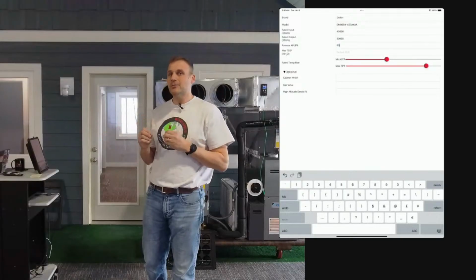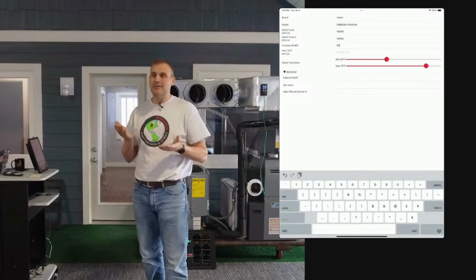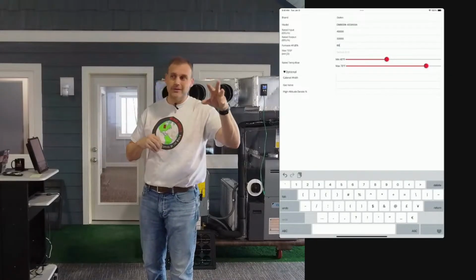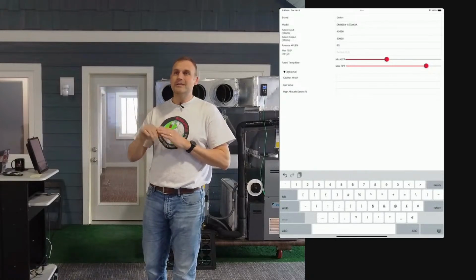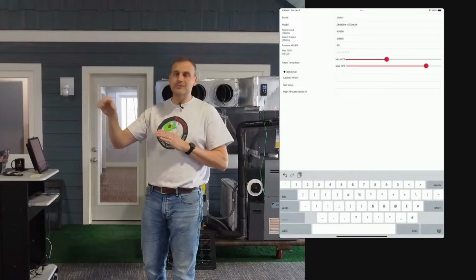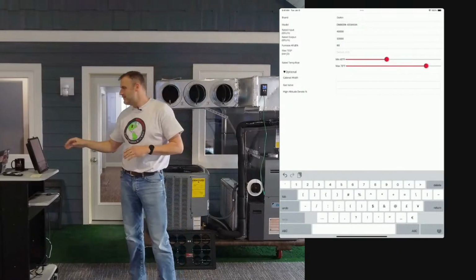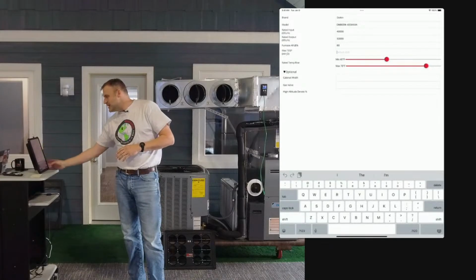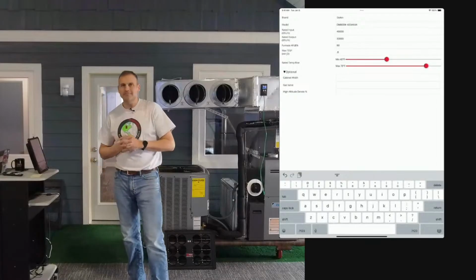So here's a switch that we've most recently made. It was becoming a challenge with programming, having to toggle it on, toggle it off, enter it, not enter it, do this, do that. So we said, okay, enough is enough. We're going to put it in as a default, okay? Default, it's always there, always adjustable. That's how we're handling total external static pressure now, and we've defaulted to 0.8. We can change it if we want to. We're going to put 0.8.